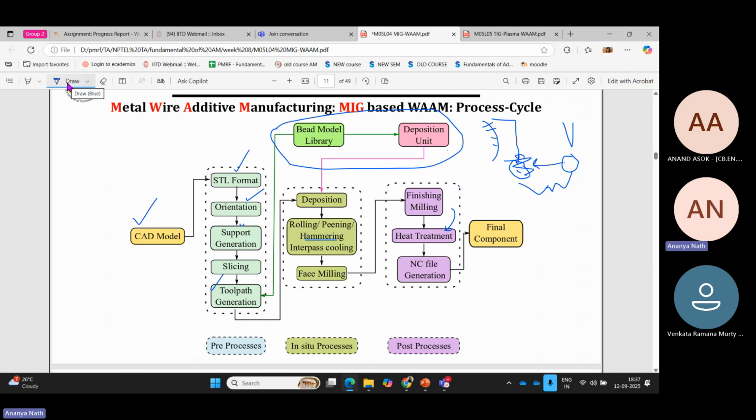What he was discussing is after additive manufacturing, we are going to get a very high temperature part. So what will happen at the time of face milling? The answer is if your heat gradient is very high, then your cooling rate is also high. So even just after the deposition, the temperature will not be more than 300 to 500 degrees centigrade.